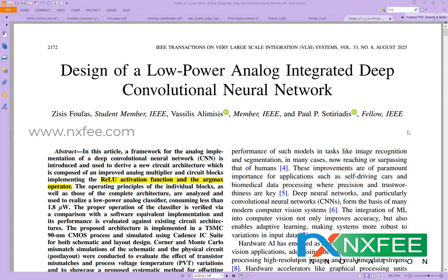A 3x3 kernel multiplication array is also implemented to enable efficient convolution operations with reduced transistor usage, smaller area, and minimized interconnections. The novelty of this work is the realization of CNN computations in a back-end transistor level analog design, which offers low power and compact integration compared with conventional analog designs. Performance is evaluated through detailed comparisons of MOSFET count, power, area, and delay between the proposed circuit and the existing 90 nanometer CMOS technology.